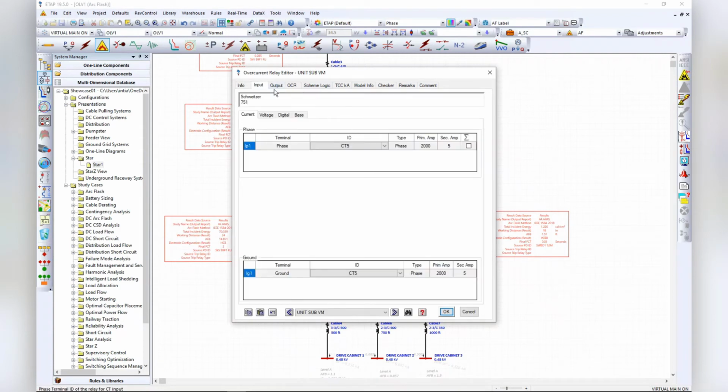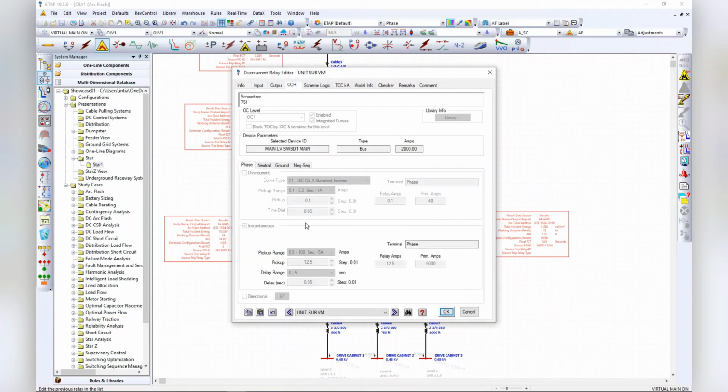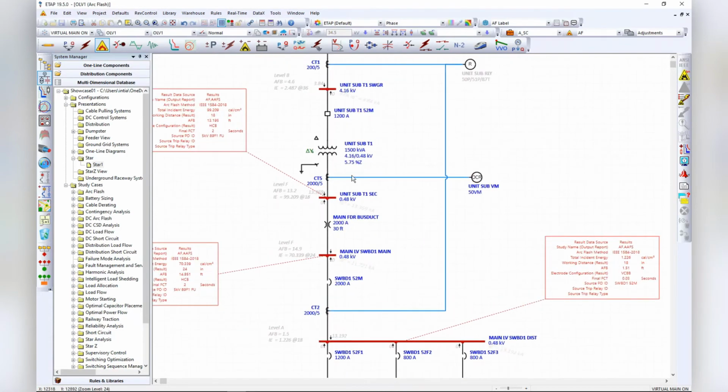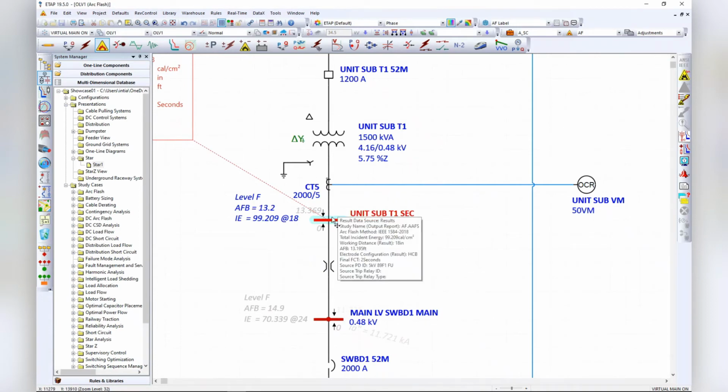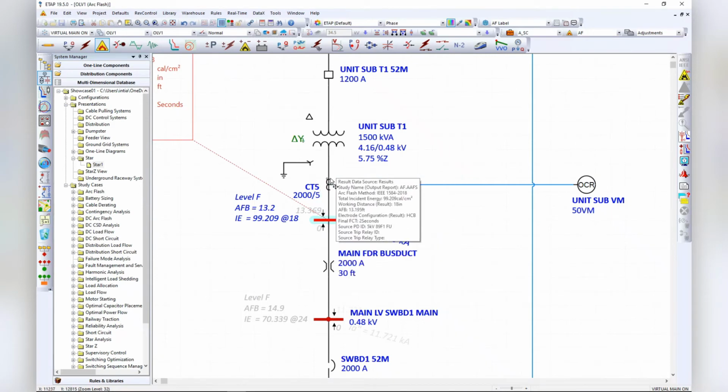And what that's going to do is be another instantaneous override, but it's just going to be looking right at the transformer. So you put your CT right on the transformer. Now, if this bus represents the transformer terminals, does it go upstream or downstream of this CT? That's a discussion about how the transformer is being built.